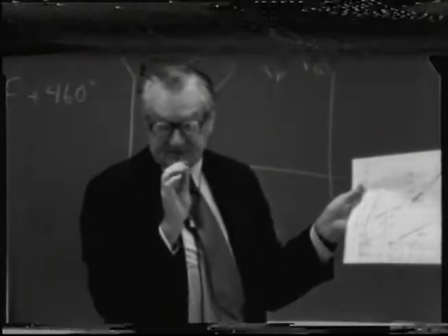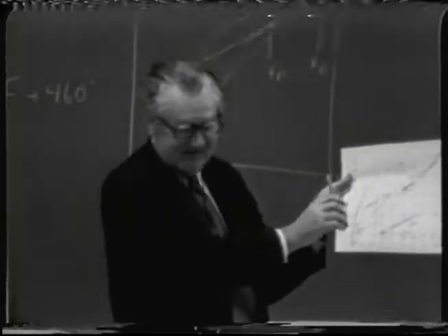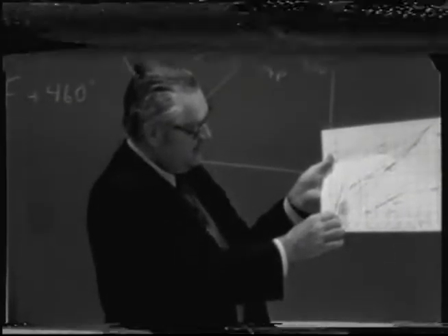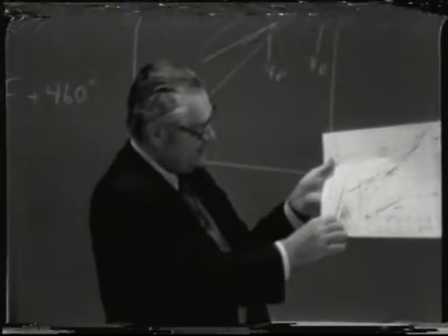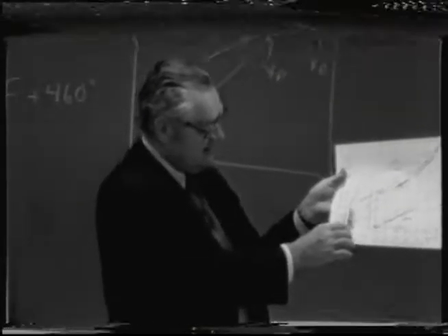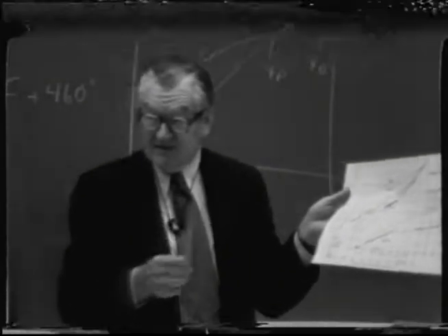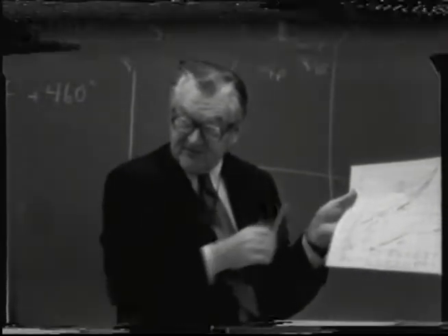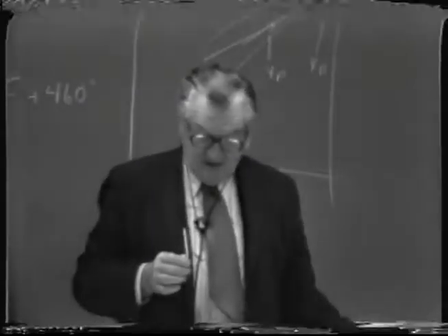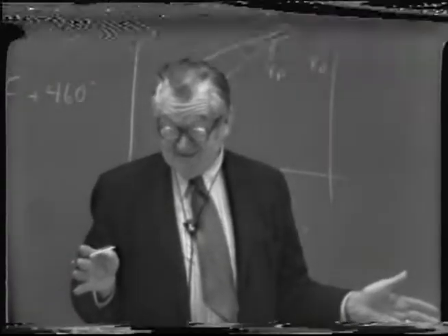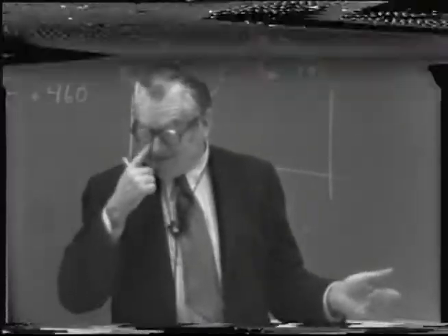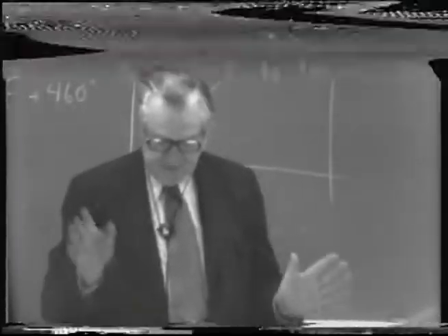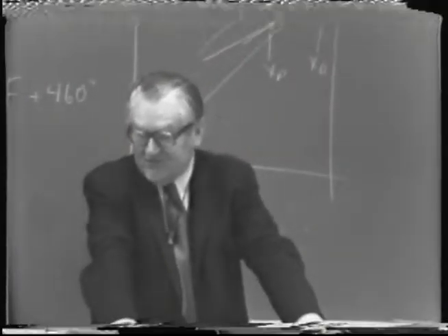I don't know if it would or not, but the fact now we're considering the vapor on the lowest tray would be a slightly higher alcohol concentration than the feed because of this effect of the Q line. I'm not sure that's the answer. It may be that I use some other basis to estimate the temperature and, that I don't remember now. But the net result wouldn't have very much effect anyway.